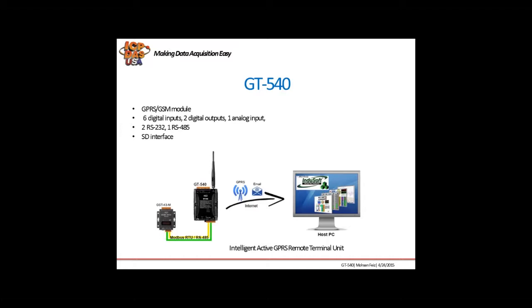It can be used in M2M application fields to transfer the local I/O or Modbus device data by GPRS by the defined period, or as a digital input or analog input trigger. The local I/O data, as I said, can also be stored in an SD card to become a remote data logger.